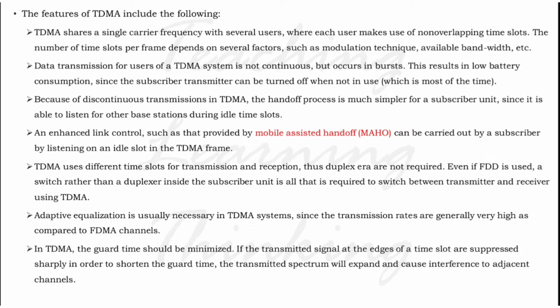And the fifth one is that TDMA uses different time slots for transmission and reception. Thus duplexers are not required. Even in FDD, a switcher rather than a duplexer is used inside the subscriber unit, which is required to switch between transmitter and receiver in TDMA.